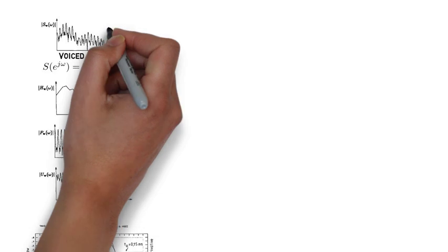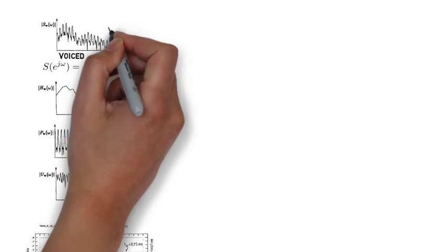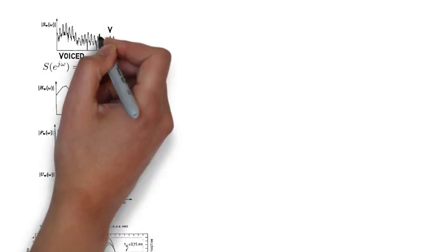And it's not even so simple as that. You can see that there's this low-frequency voiced band and this high-frequency unvoiced band, but right here there's 3 harmonics that are very clearly voiced. And then just below those, there's this section of about 2 harmonics that look like they're primarily unvoiced.